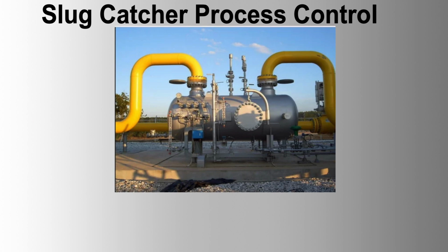Practical example. Application. Use MPC to control the liquid levels and gas pressure in the slug catcher. Advantages. MPC can handle multiple inputs and outputs simultaneously, predict future disturbances, and optimize control actions to maintain stable operations.